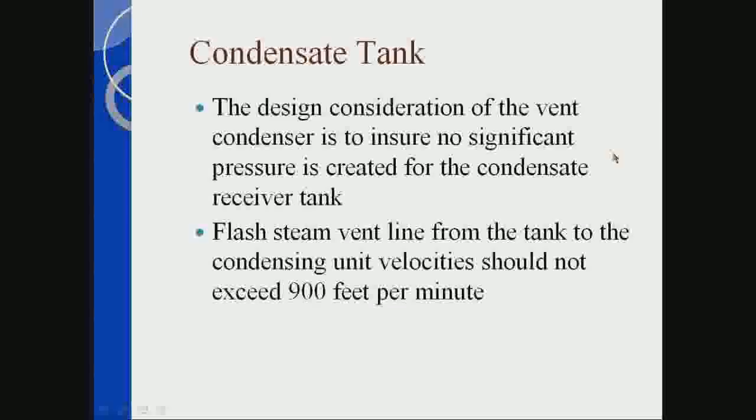And the heat sink is the makeup water going into the deaerator. So we pick up those BTUs and go into the deaerator. Even today, we don't even allow the vent off the deaerator to happen. But remember, with the condenser, it has to be properly sized so I don't create vacuum and keep the non-condensables inside the deaerator. I want to make sure that I am venting the non-condensable gases out of the deaerator.